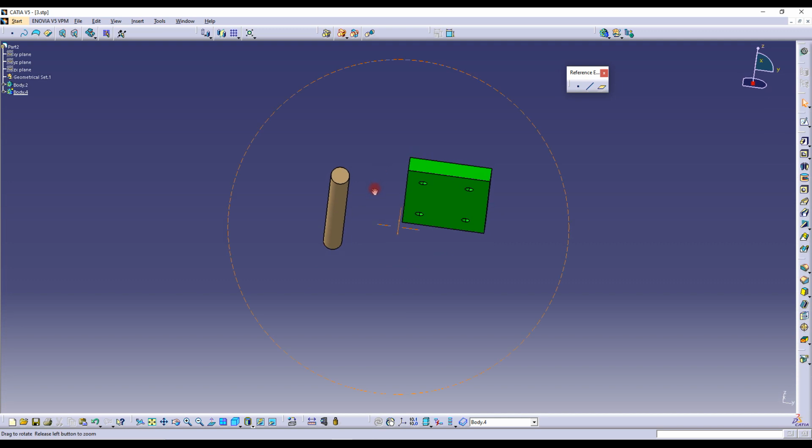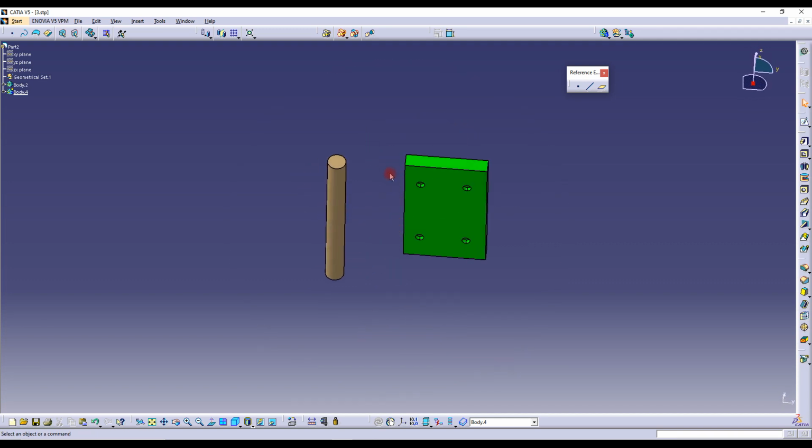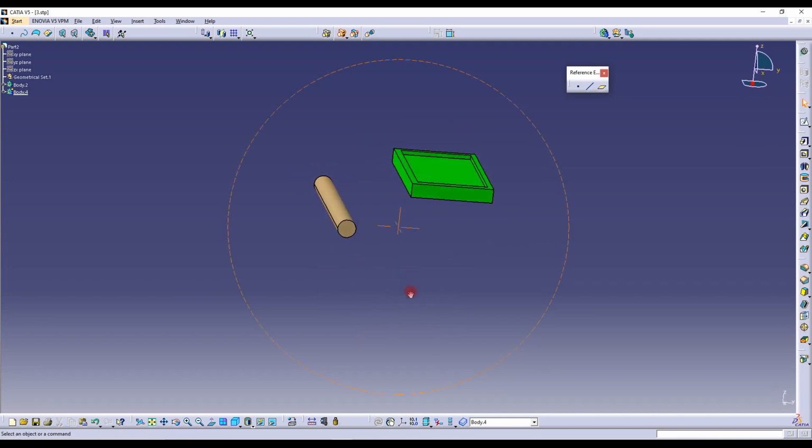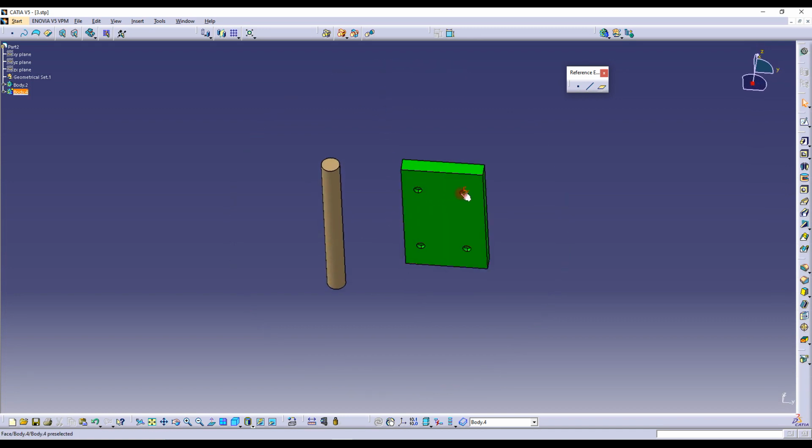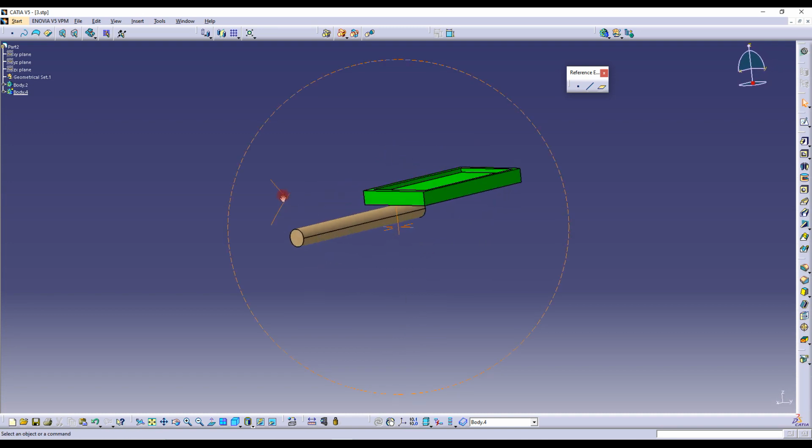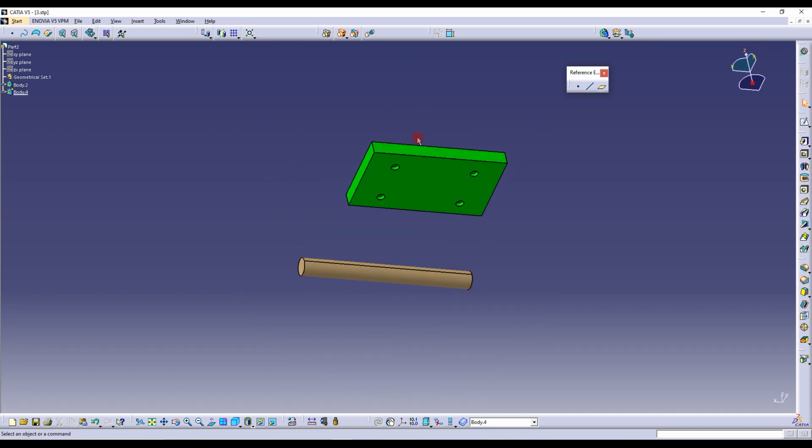So for that, we can design one single bracket which is accommodating all the 4 holes, or you can design one bracket which is replicating 2 sides. So which is mounting over here in 2 holes, and then that same bracket is used over here and mount it over here in these two holes. So we will do that. Let's see how we can do that by designing a sheet metal bracket for this application.